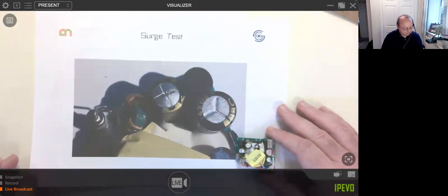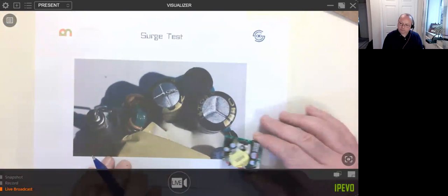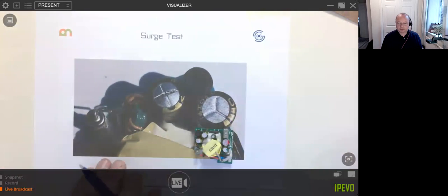Power supplies have to be tested to 2000 volt surge, and they do 500, 1000, 2000 volt surge. It's got to be able to handle the surges for 10 cycles, and it must be absolutely okay. This thing gave an enormous loud bang and a very funny smell. If you remember when we were kids, you had cap guns. And remember how they smelt? That's what this smelt like.